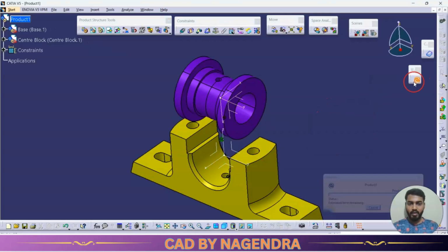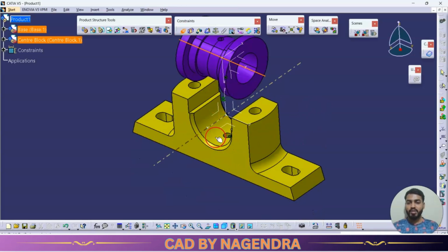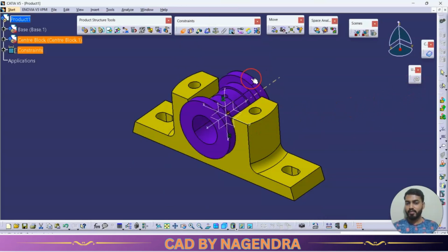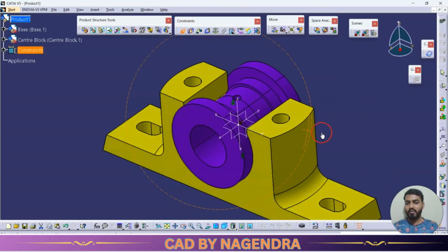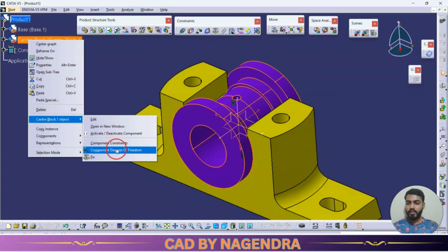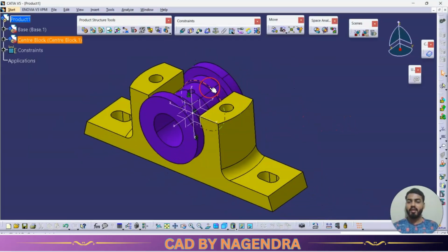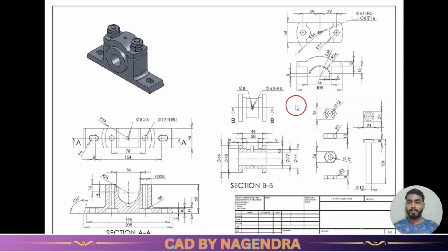Okay. Again, if we update, it will come straight to that. Then this central axis should be straight to this. So we'll make it coincidence again like this. Properly, it will go inside and fix there. Then if we check degrees of freedom for this block by using this, you can see there is no degrees of freedom. Then we can consider that this block is fixed properly.